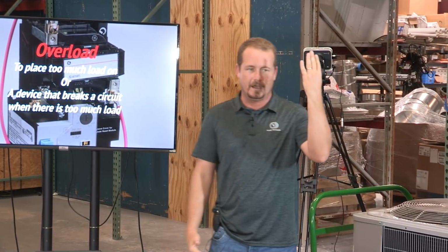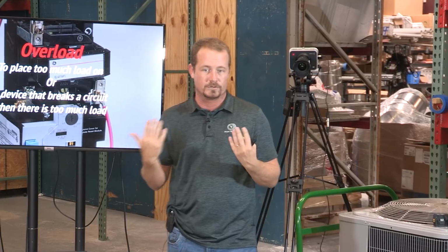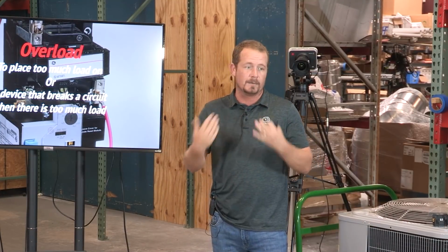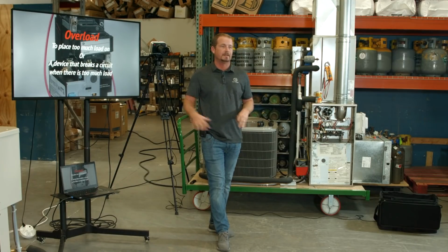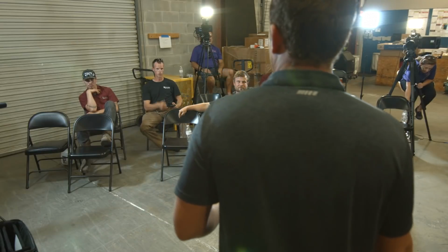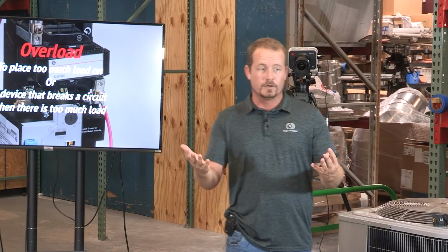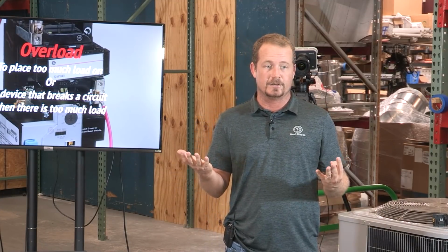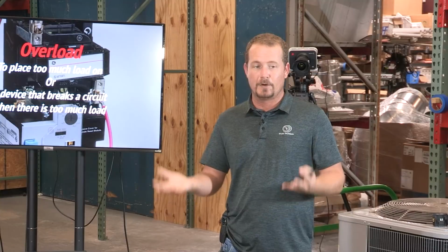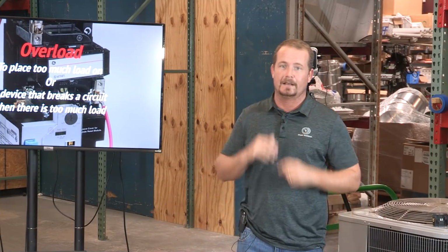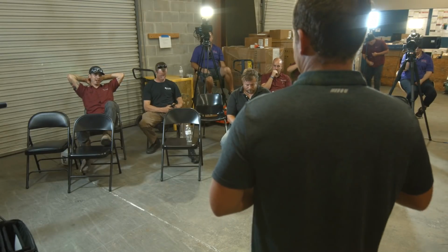Overload conditions with physical overload and electrical overload as far as too much current, those are proportional to each other. So with a system that's just come out of defrost, what happens to your suction pressure when the evaporator coils are all really warm? Your suction pressure is really high, right? So when suction pressure is high, what happens to your refrigerant density in your suction line? It's more dense, right? Higher pressure, more density. So more refrigerant is coming into that compressor. What happens to your compressor current when that happens? Goes up, right? We talked about that.